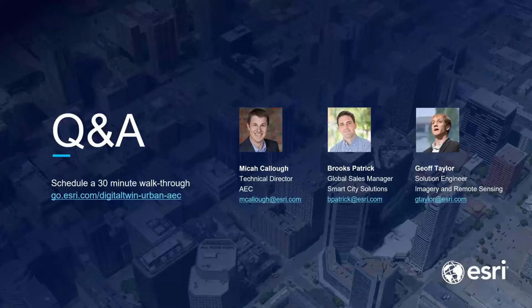With multi-patch buildings, they're discrete features, and whenever you publish these buildings as a scene layer, what actually gets published with them is the 3D, but also a companion layer, which is a feature layer that holds all of the attributed information and can be updated obviously more rapidly than you can a 3D cached file.